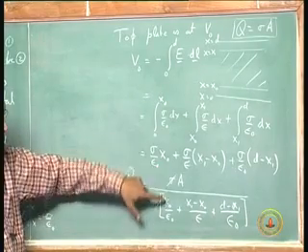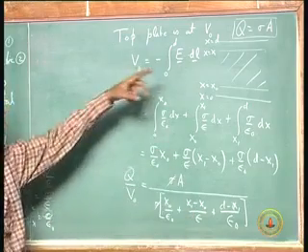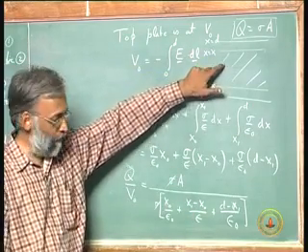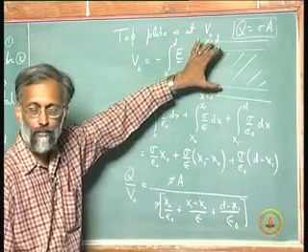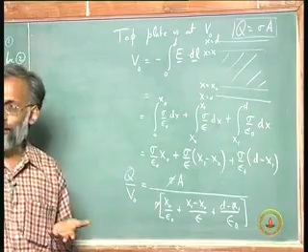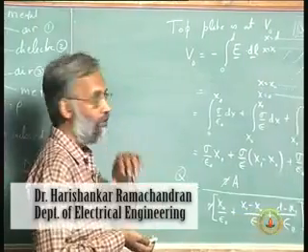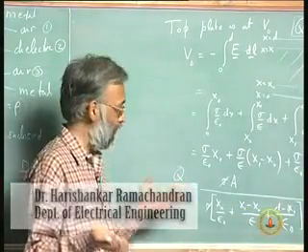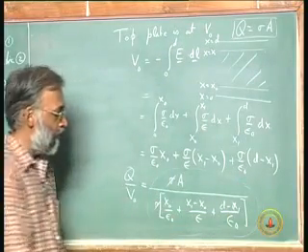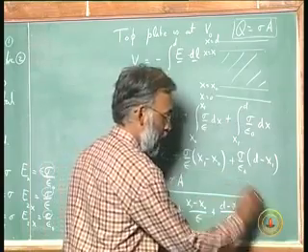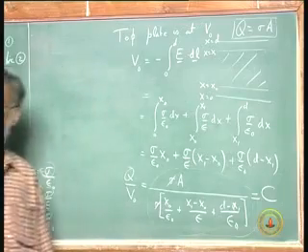It depends on device parameters because it depends on A, it depends on epsilon, which is the material of this dielectric, which dielectric I put in. It depends on the spacing, on the gap size and on the thickness of the dielectric. All of these are based on how I made this capacitor. It does not depend on what is happening in the rest of the circuit. So, this is a quantity that depends only on the device physics, and therefore, it can be defined independent of anything else, and so again I can define it as a capacitance.